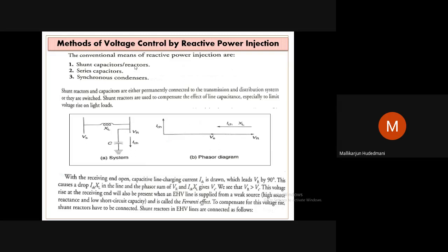So that's why this method is one of the simplest methods practiced in highly inductive load, large industries, where we find induction motors in large number. Higher capacity induction motors being switched, definitely that absorption and that effect on the local system adversely cause their total operation, or the high suction of current during the starting makes their total system go a little inferior. In such scenario, local compensation at the load terminal itself is done by compensating by capacitor itself.